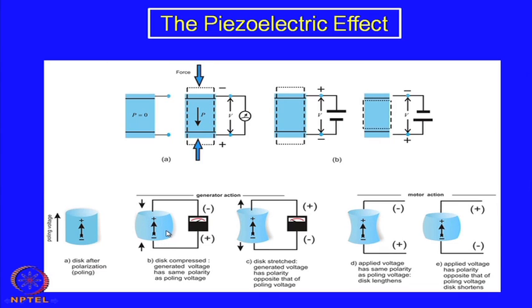So, that means you are applying a stress in this poling direction, but there is a component of stress in the orthogonal direction as well, and that is making it increase its dimension. And in a similar manner, if you put in tensile load, there will be a reduction in the dimension, again because of the same reason.